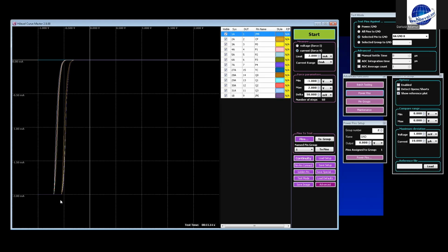In the case of the automatic curve tracer, all you have to do is define those pins, define your type of test and parameters, and hit the start button. And you are done. You see, it took 10 seconds to get the measurements for 13 pins. This characteristic is with just one pin, the ground of the device, connected to ground, and all other pins are disconnected. If I change the mode, this is very hard to do with external instruments.